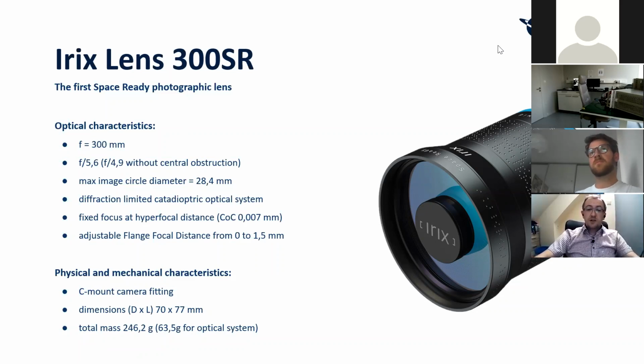That's why our optical engineer, when he got the brief, knew that he must provide a very wide tolerance for any changes of the lens housing size. I mean, also the tolerance of the optical surface thickness, the distances between lenses, and also the thermal expansion of the glass and of the metal.